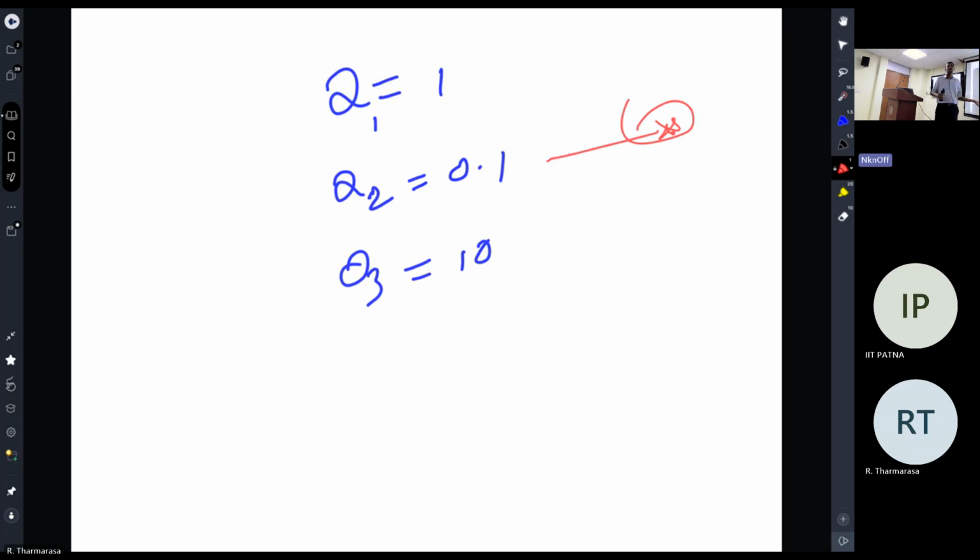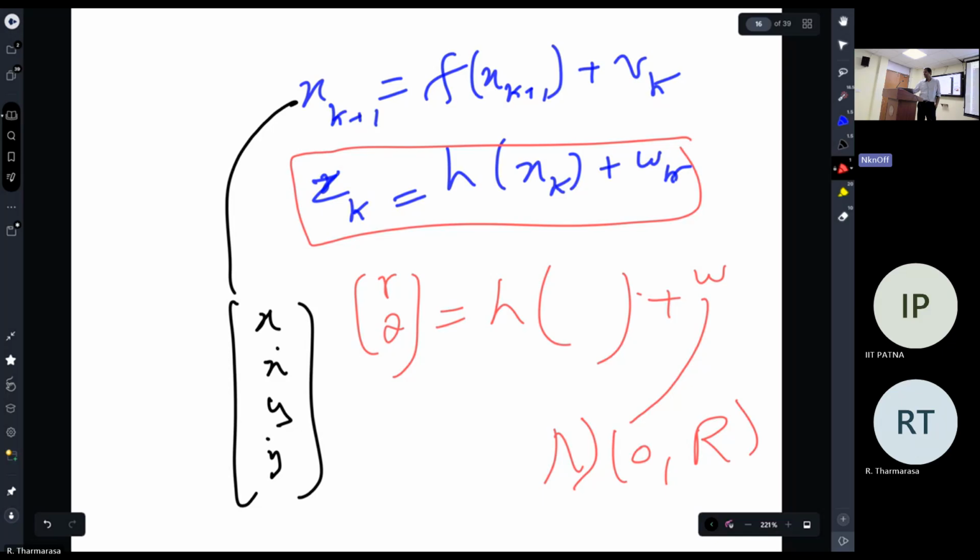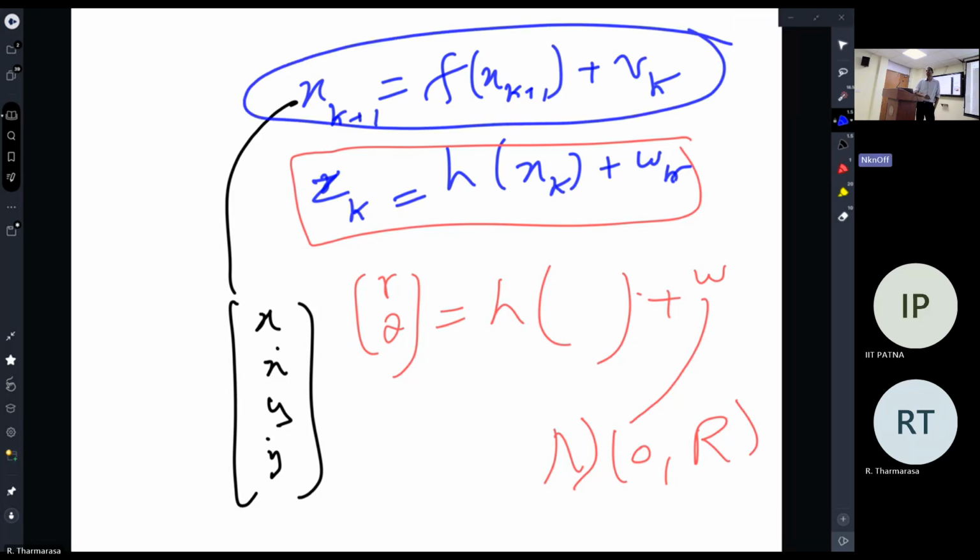Okay, I say that is not the best choice. Go ahead. It's based on the trust in the sensors. Pardon? Based on the trust in the sensor, or in the process model that you have. I again repeat that the process noise has nothing to do with the sensor. When you define that, you never think about the sensor that you are using. It's only to capture the target's motion.